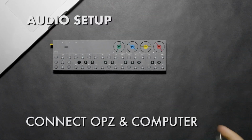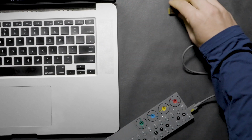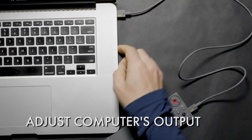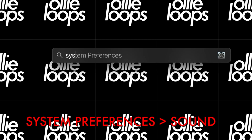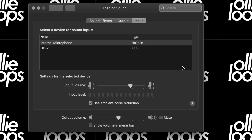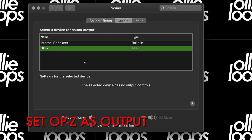First, connect the supplied USB cable between the OPZ and a computer. Now we need to adjust the settings of the computer to route audio to and from the OPZ. On a Mac, it's pretty easy to do this. Go to System Preferences, select Sound. You should see the OPZ listed both under an input and as an output. Under the Output tab, select the OPZ from the list, and now audio should play through the OPZ.